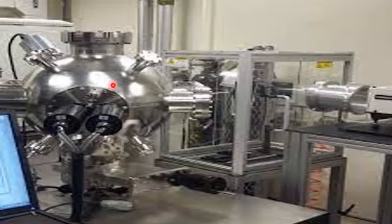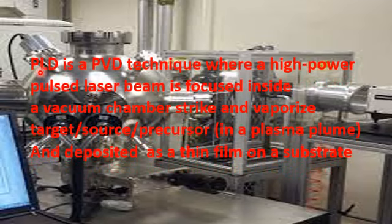So dear student, in a nutshell, pulse laser deposition is defined as a type of physical vapor deposition process in which a high-powered pulsed laser beam is focused inside a vacuum chamber to strike and evaporate the target or source material, and then it is deposited as a thin film onto a substrate. Let us make this definition quite simple.